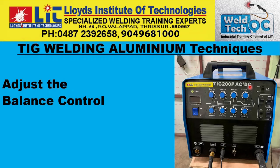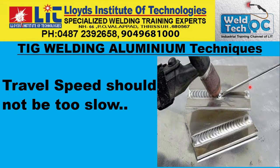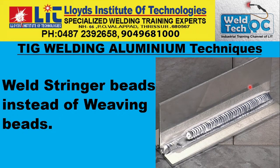You can start with 50-50, 30-70, or according to the requirement of the base metal. And travel speed should not be very fast while you are welding aluminium. That please be noted. And it's always recommended to use stringer beads instead of weaving beads.